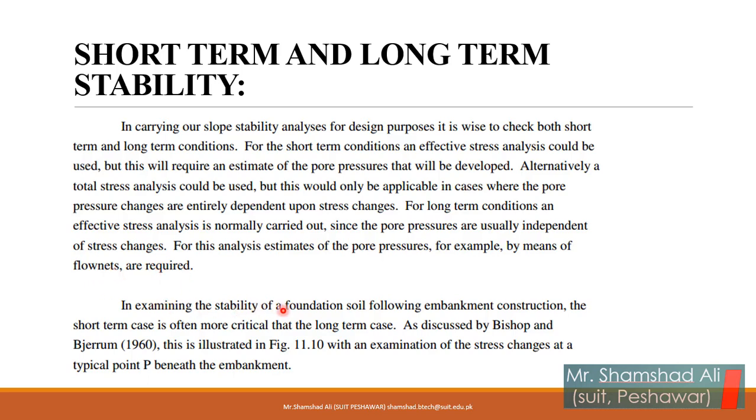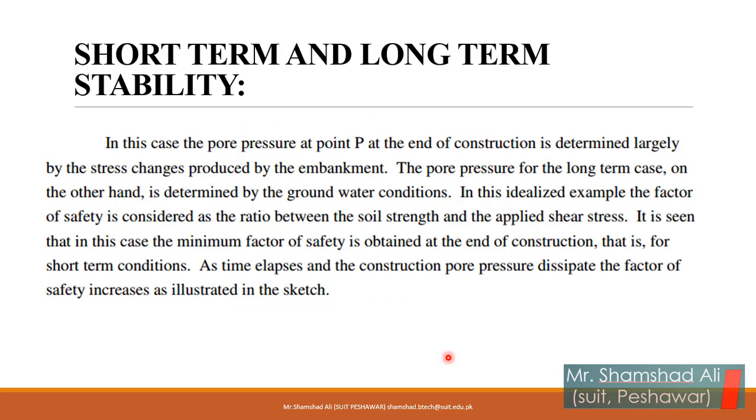In examining the stability of a foundation site for a following embankment construction, the short-term case is often more critical than the long-term case. As discussed by Bishop and Bjerrum, 1960, this is illustrated in figure 11.10 with an examination of the stress change at a typical point P beneath the embankment. In this case, the pore pressure at point P at the end of construction is determined largely by the stress change produced by the embankment. The pore pressure for the long-term case, on the other hand, is determined by groundwater conditions.